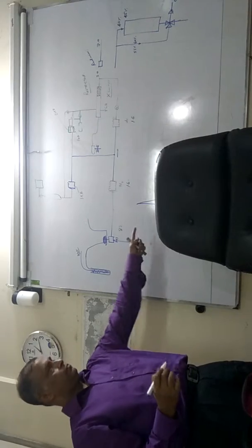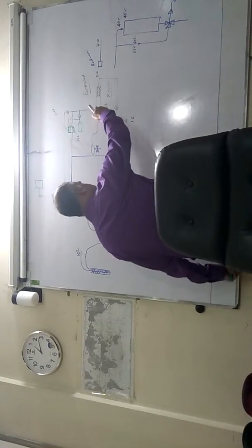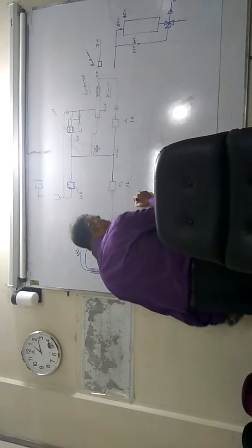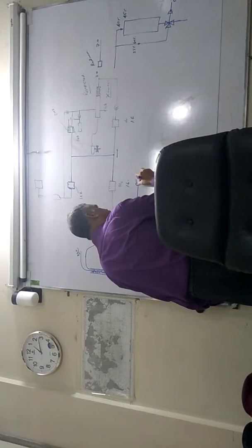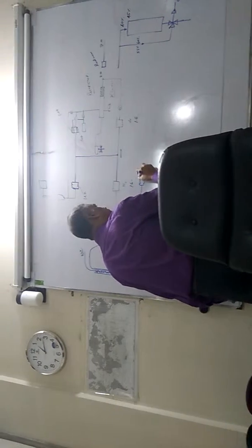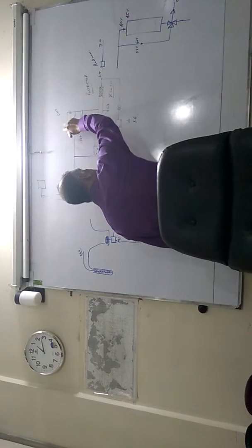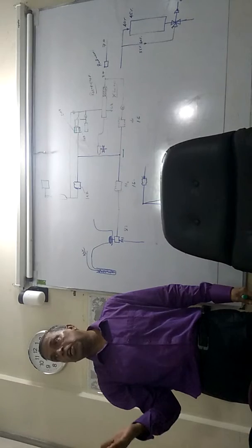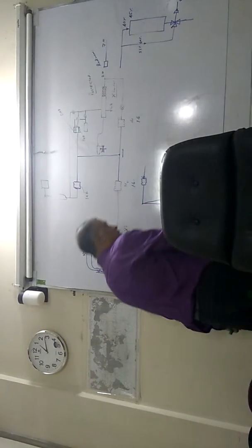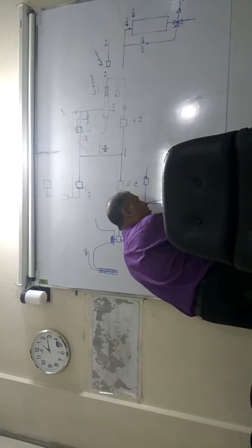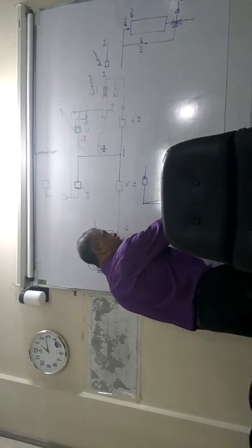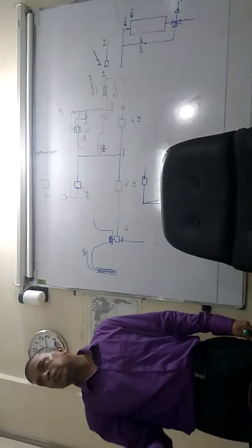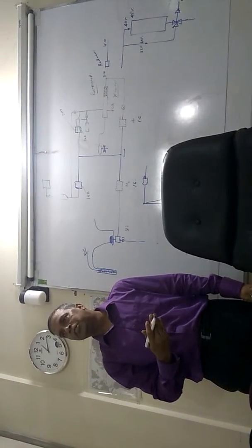Yes? This pressure increases. Because of the proportional action bellow working here, that high pressure also goes and works on the black bellow directly, which is our proportional action bellow. Now, with the deviation, pressure increases. That high pressure also causes the flapper stop to move in the opposite direction of the deviation.